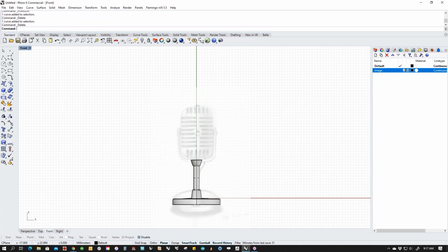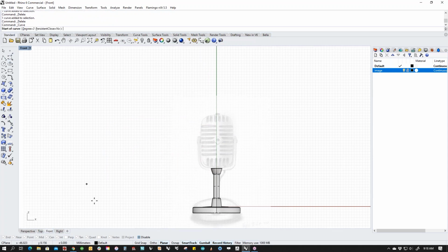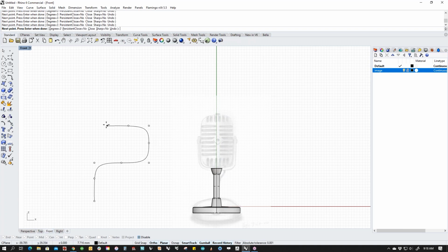And I can hear what you're saying. Well, what if I have to make a shape that has more than one corner in it? Same thing. Lead in, 1, 2, 3, 1, 2, 3. That's the first one, 2, 3, 2, 3. So if we look at this, this is in its simplest form, right? This is the lead in, that's just the anchor for the curve. That's the first corner, 1, 2, 3. If I want to tighten that up, I come over here like this.